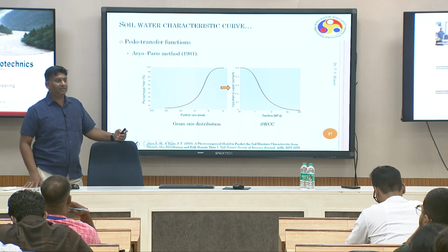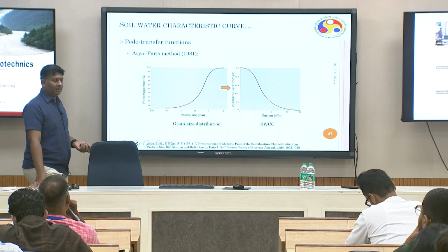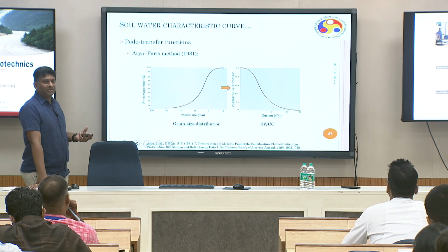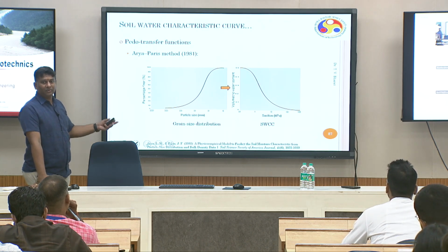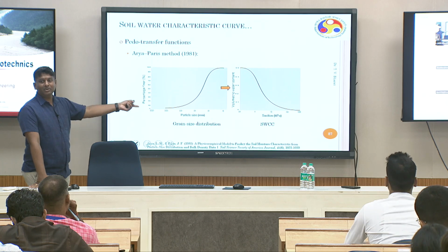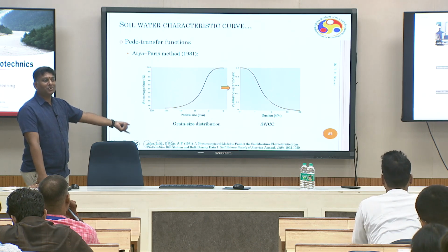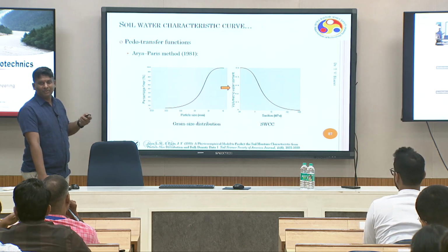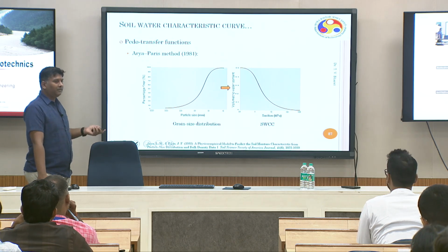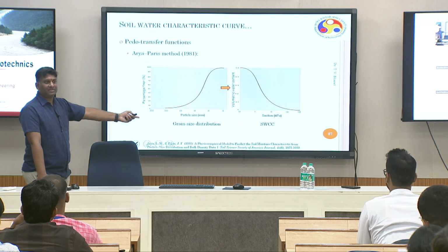We have done that study in fact for the Shillong Nihu site previously, which is published. So these predictions are possible. These are physics-based predictions. They are possible once we have a solid understanding of the soil water characteristic curve. Secondly, the flow characteristics. When infiltration takes place into the ground, or evaporation takes place, you require drying and wetting SWCCs. Without that, it is not possible, right? So the flow characteristics can be understood using this itself. That's why understanding these characteristics for a given soil is important.